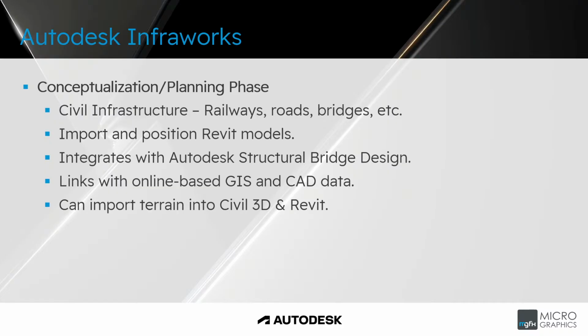You can import the terrains generated within InfoWorks into Civil 3D and Revit, which is awesome, because oftentimes within Civil 3D, what we lack is the terrain data. Now, of course, there is a level of accuracy that you need to be aware of within InfoWorks. As we know with any sort of GPS data, there is a margin of error, but it's also really cool if that is what you've got. It is incredibly sufficient to get something on paper and to start running numbers.